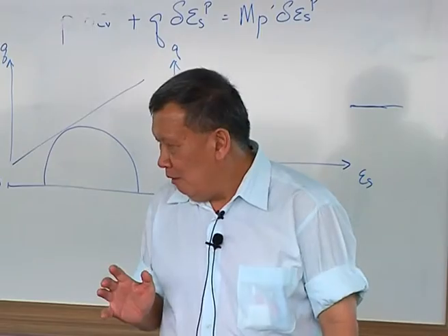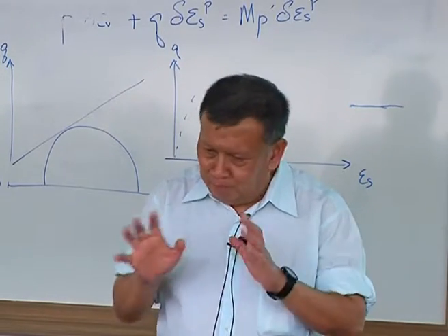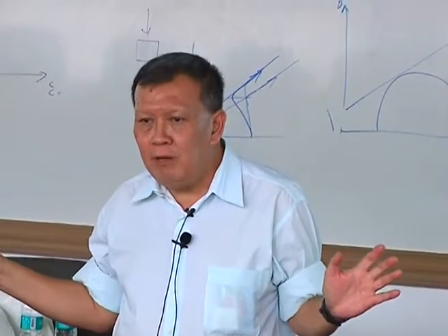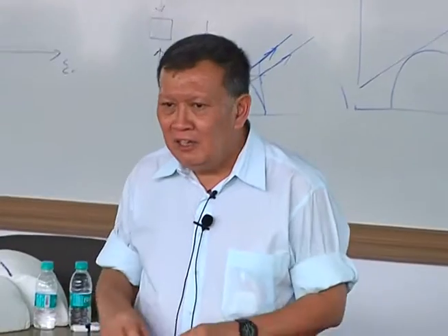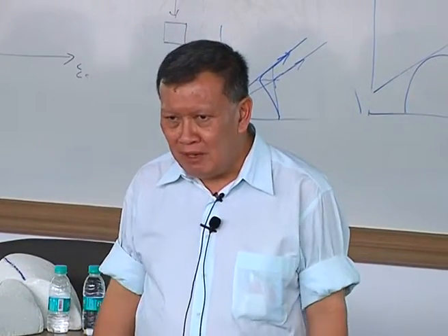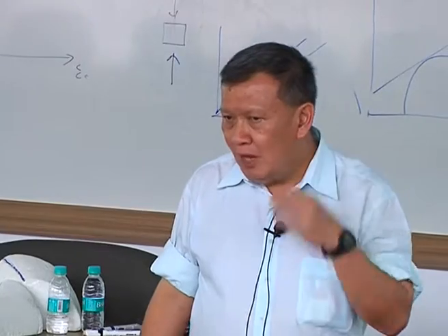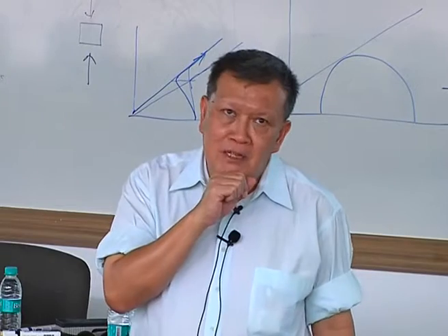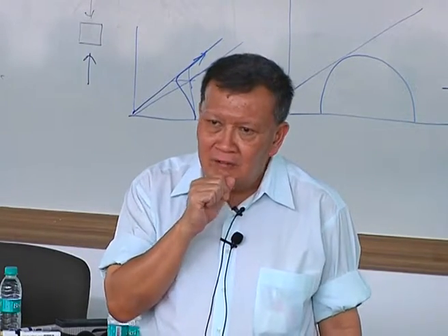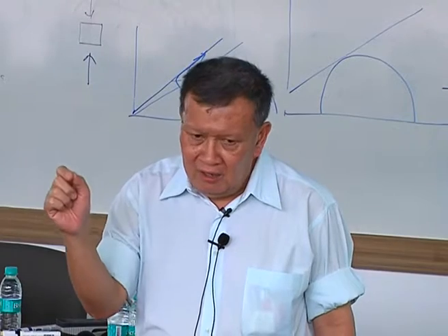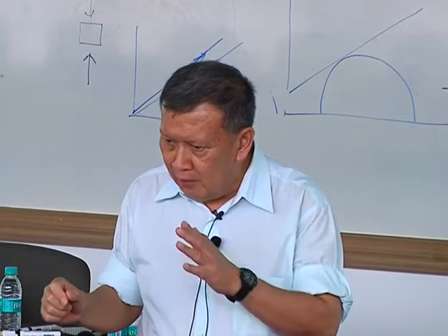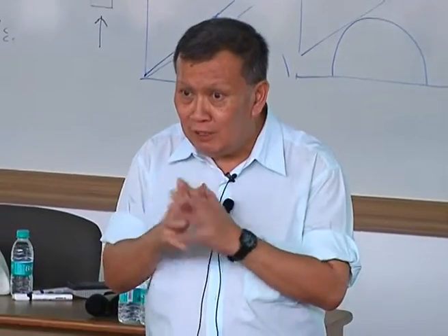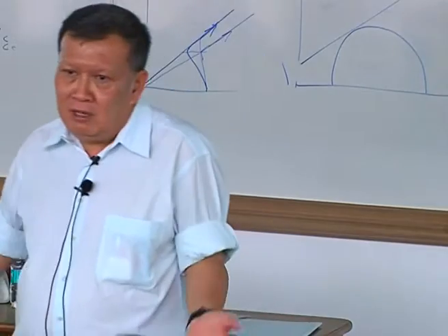So with that problem, the first thing I did was to do a sensitivity study. Immediately I found that, wow, it's almost completely proportional to the stiffness. Then I know that this is a problem that is governed by the stiffness. So basically, I just model it as a Mohr-Coulomb with an angle of dilation. I think I was using Abaqus. I was using like 0.1 degree or some very low angle of dilation. And then I use what I believe to be a reasonable modulus, E50, for that soil. So I went for it and it worked out okay.